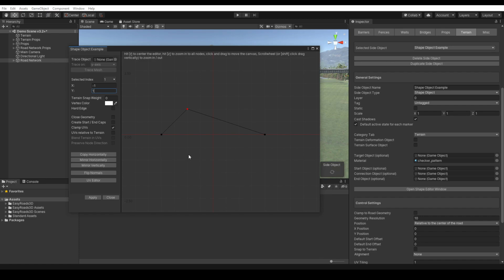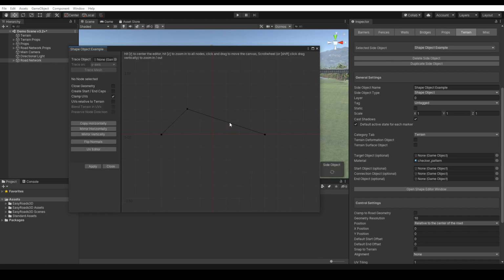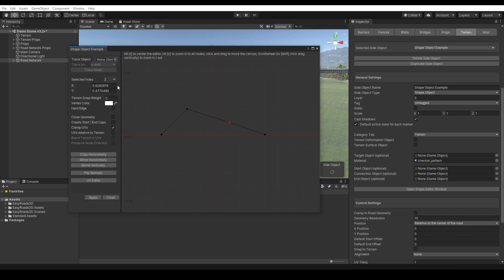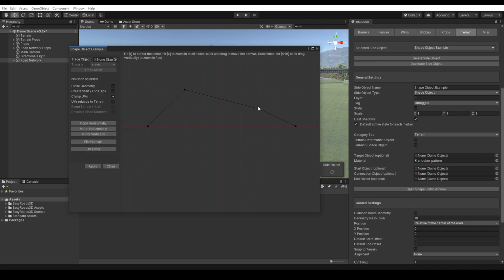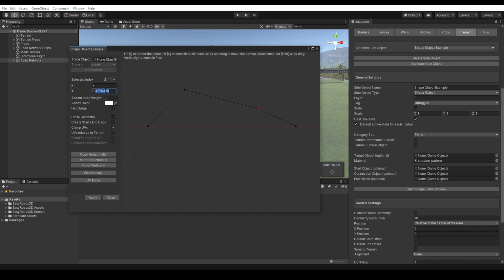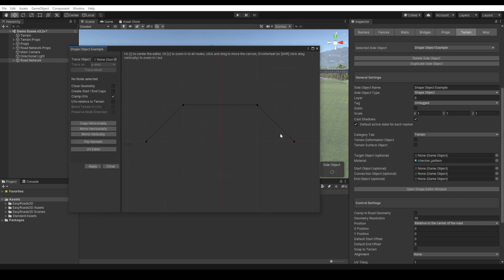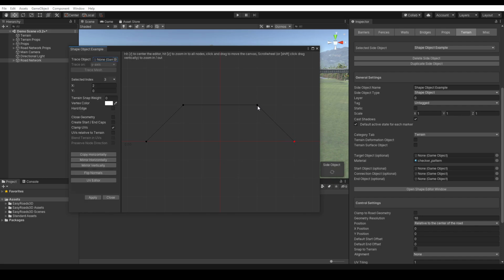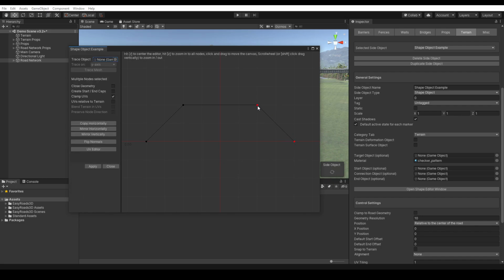So we can double-click to add nodes. The nodes will connect. We can insert nodes at the mouse position by pressing the Control key and double-click. Selected nodes can be removed with the Delete key. All actions can be undone. We can select multiple nodes by pressing the Shift key and then select other nodes. The selected nodes can be moved or deleted.